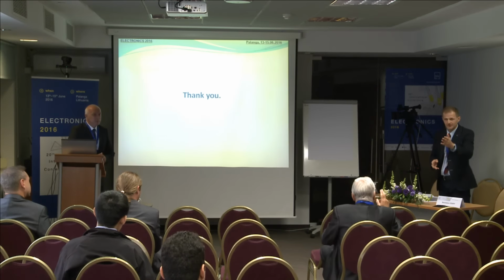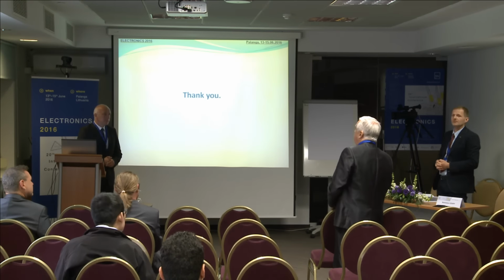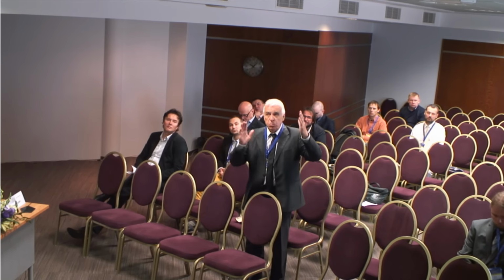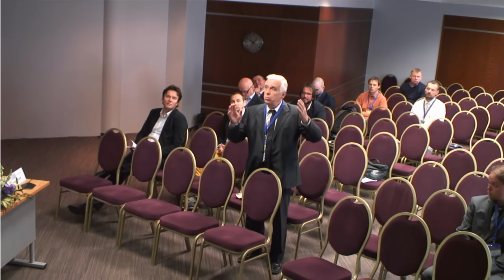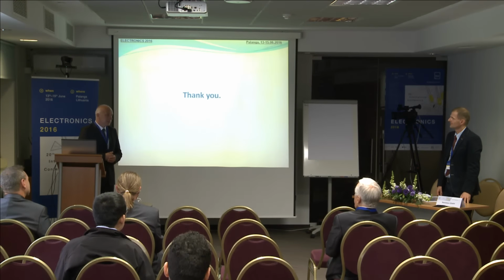Thank you. Just a little comment. It's a very important thing, since nowadays, as you know, it is recommended to use in the home 2 separate installations, one AC and another DC, to avoid the losses due to converters when you have, for example, a solar battery, to avoid the conversion from DC to AC and supply directly the loads which are DC loads, like lamps, LEDs, something like this. In the future, old buildings and new buildings would probably be equipped with 2 installations. Therefore, your work is of great importance. Yes, as I said, the DC applications are rising, and of course the hazards also will rise. Thank you very much.